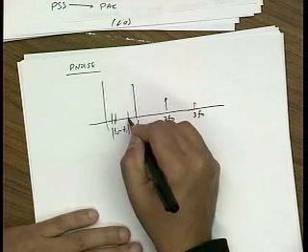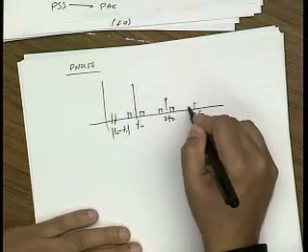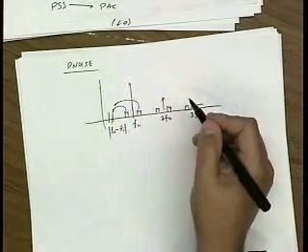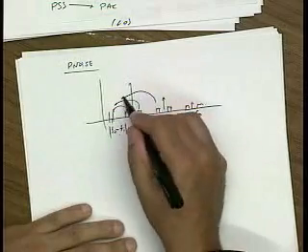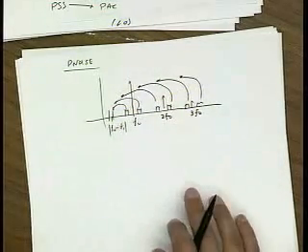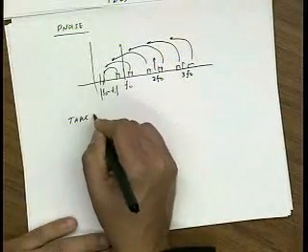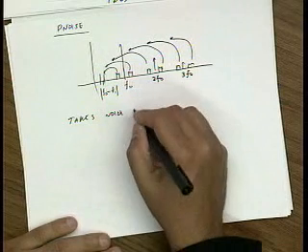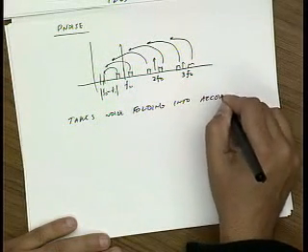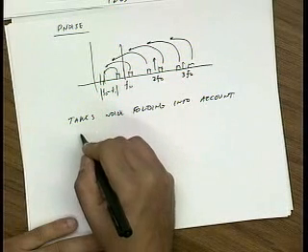Then it knows that the noise folds. It knows what the noise spectrum looks like. Let's say it's flat, like I've shown here. And it can calculate all the noise folding as before. So P-noise takes noise folding into account. And in order to make it work correctly, you have to specify, again, the sideband.